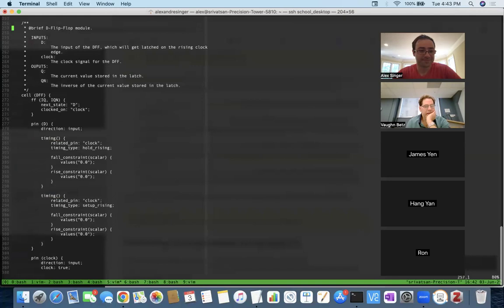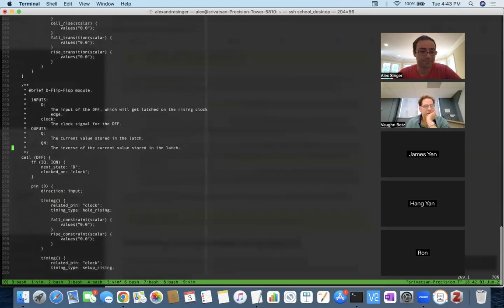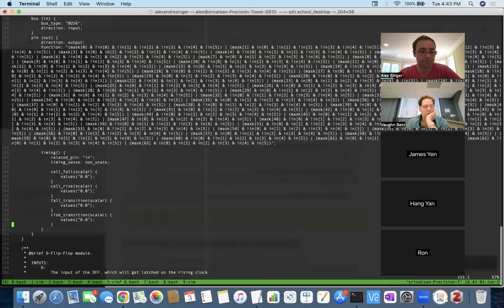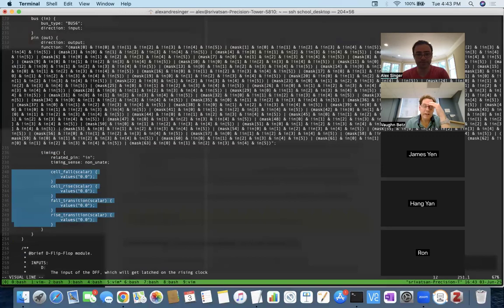One of the things that's in there, I think I know what it is: you've got rise times and you've got fall times, and then you've got transition times, fall and rise transition. So I think what you've got here is what's often called a 4 point delay model. There's a delay to the cell, and then there's a slope too. So its output starts changing after a certain amount of time. I think that's what it'll define the fall as, and then it has a certain transition time to fully switch. And that's done to make the delay slightly more accurate.